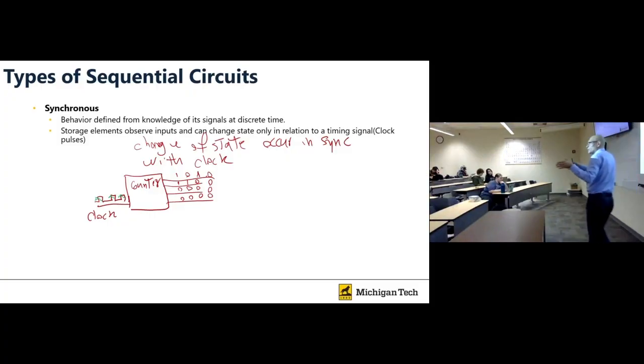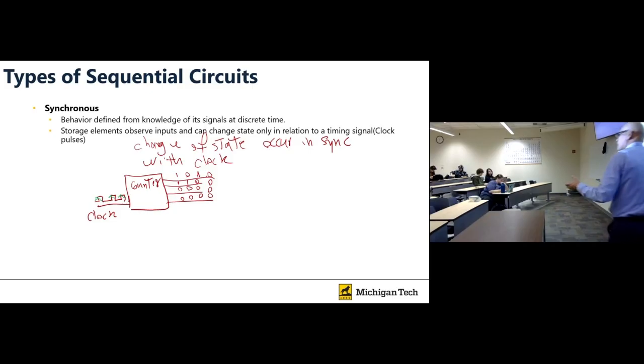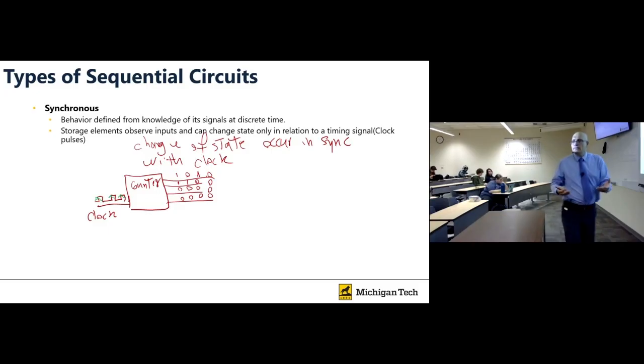Some decisions in your system happen very fast, but you need to see which decisions need more time, and we set the clock based on that delay time. That's why synchronous systems are normally slower, but more stable, because we design the system based on the clock. Problems like hazards are not going to happen if you design it right. We're going to see that later as well.